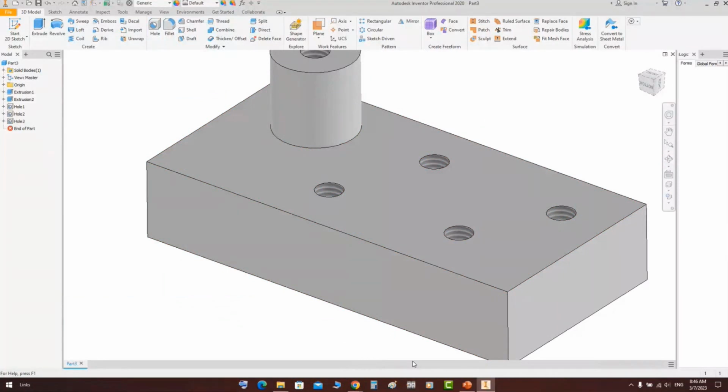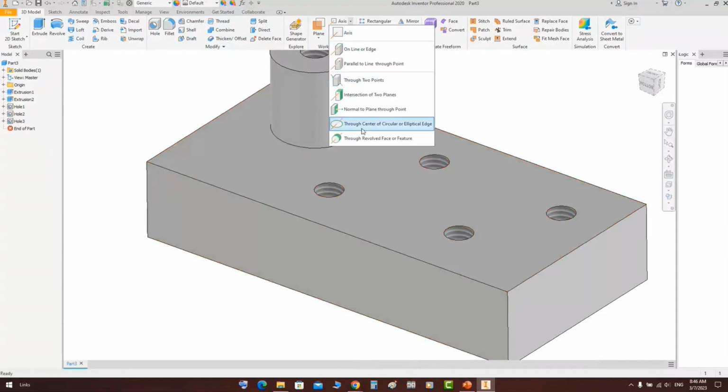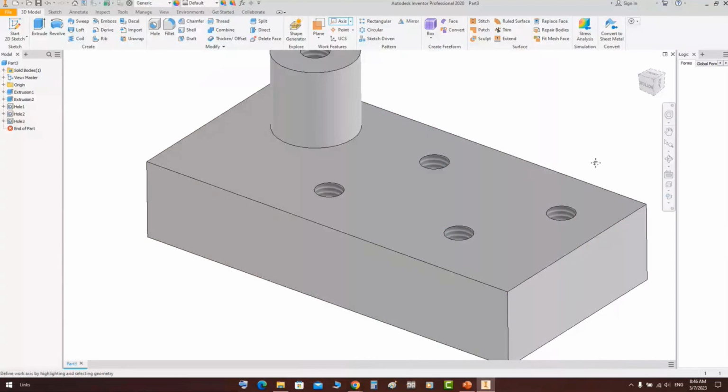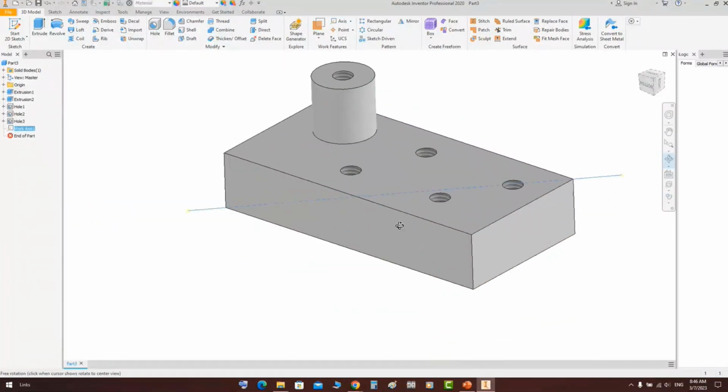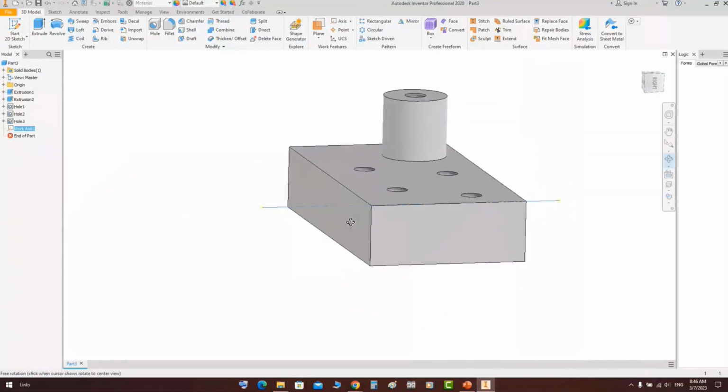And now let's know one more order regarding the axis. We will discuss it in detail, inshallah. But here, that's the ways to draw an axis. One of them is making an axis passing through 2 points. So if we select this point, for example, and that point, so you can figure that we have that axis here, go through those 2 points.